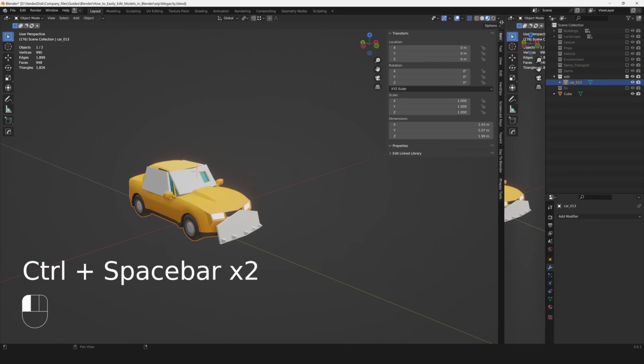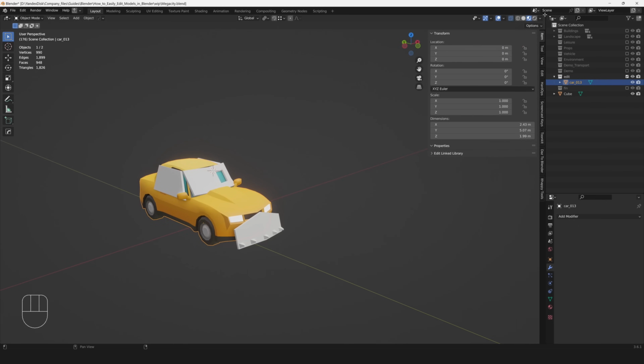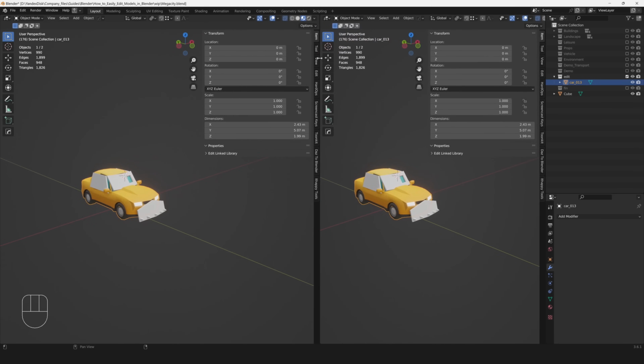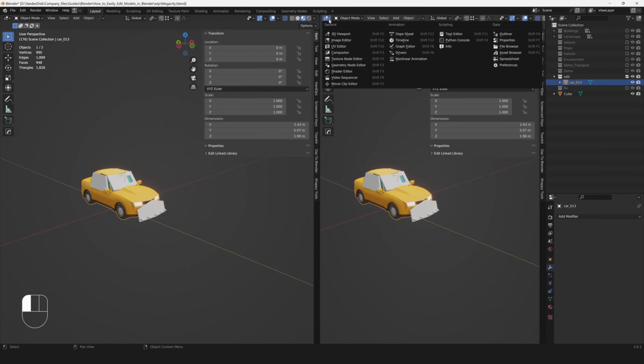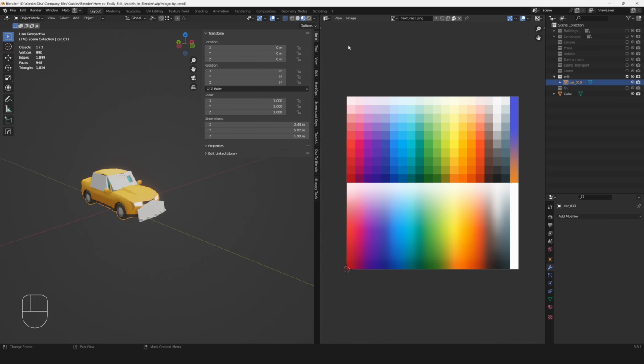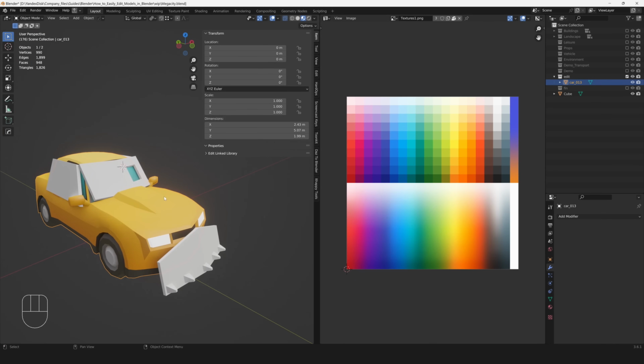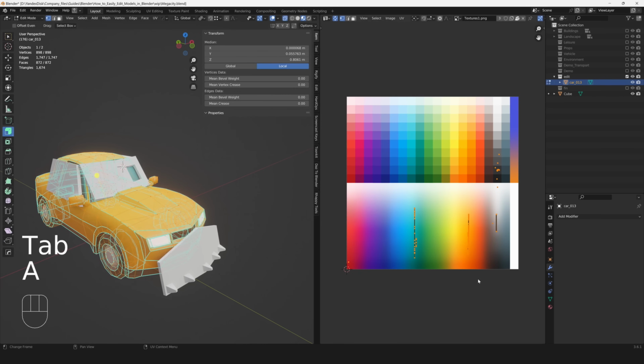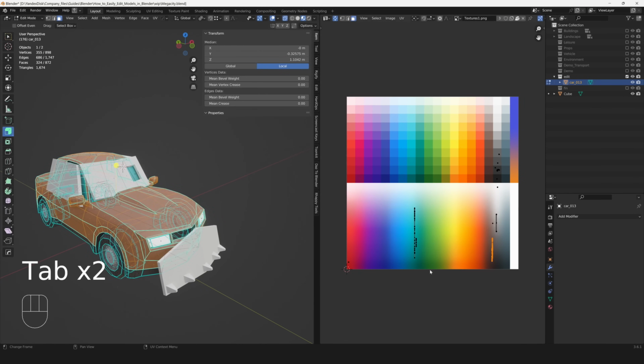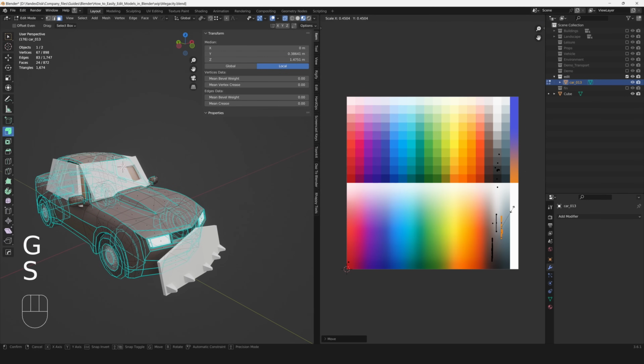Now it's almost ready to use, but it has some troubles with materials. Set your cursor to the right top corner and drag a new window from there. For this viewport we should select UV layout. Here is our texture and it has different gradients and colors. You can see our other video about this specific instrument, how you can change colors of our models. But for now I will just quickly go around this topic.